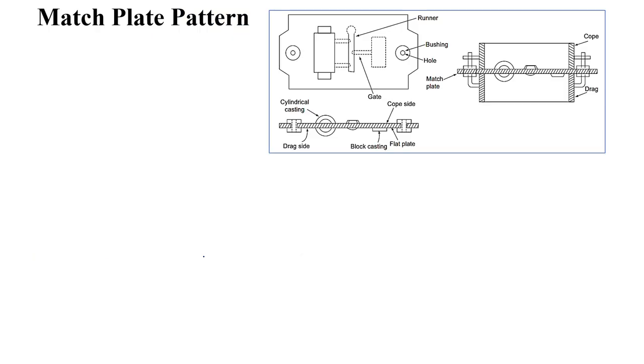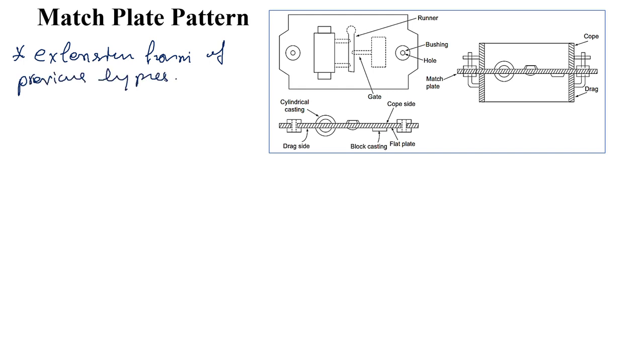Match plate patterns. The match plate pattern is the extended form of the previous types. Here the cope and drag pattern along with the gating and risering are mounted on a single matching plate.